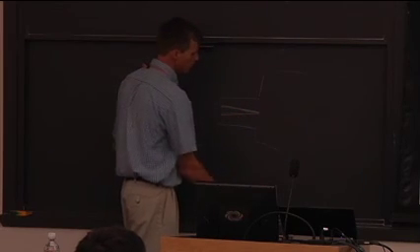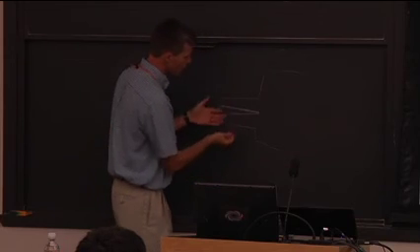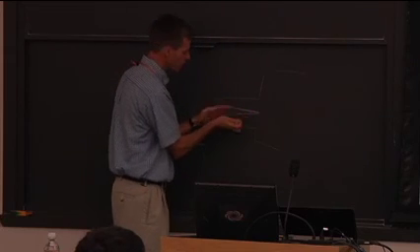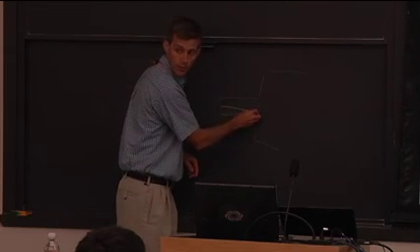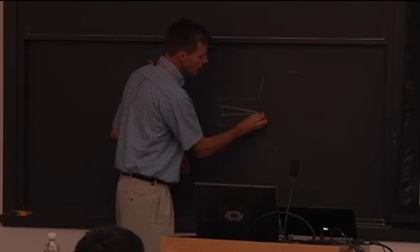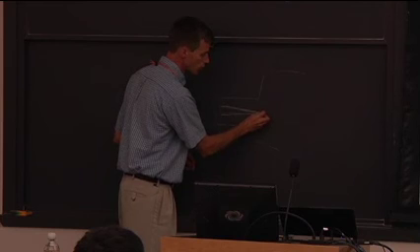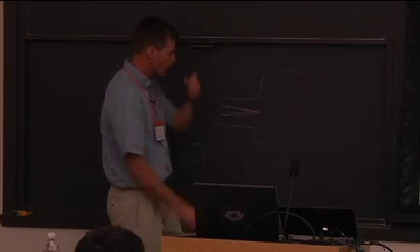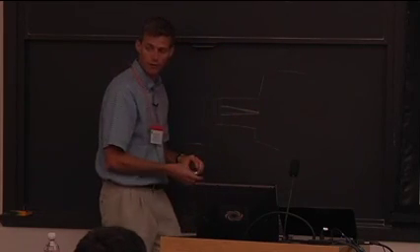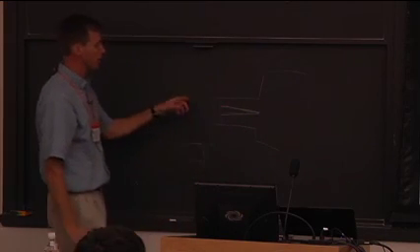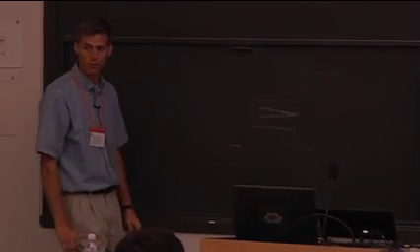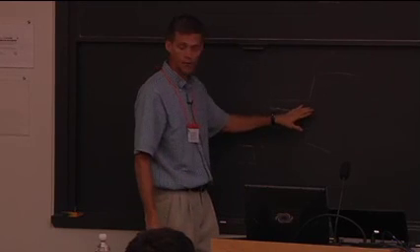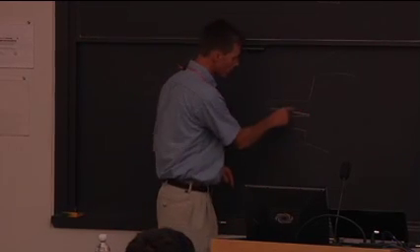The only question here is you have to design the aerodynamics such that you don't get flow separations. Really, the big challenge is as soon as you make your center body narrow diameter, it's really tricky to not make the boundary layers separate. Because of this strong deceleration of the flow, swirl flows impose a very strong adverse pressure gradient on the boundary layer. So that inner boundary layer really wants to separate. That's why you'll see most designs have a center body in the swirler. Only Alstom is one I'm aware of that really doesn't, just because of the difficulty. You can do it, but it takes a lot of careful aerodynamic design to not make the boundary layer separate right there.